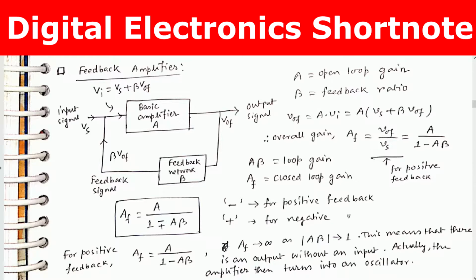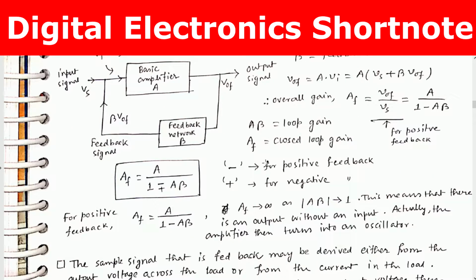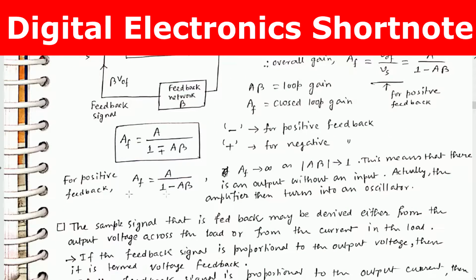Overall gain AF equals V0F by Vs. This is, for positive feedback, A by 1 minus A beta. A beta is called loop gain, and AF is called closed loop gain. A negative sign will appear here for positive feedback, and a positive sign will appear here for negative feedback. For positive feedback, we get AF equals A by 1 minus A beta. AF goes to infinity as A beta goes to 1. This means that there is an output without any input. Actually the amplifier then turns into an oscillator. This is the Barkhausen criterion: A beta equals 1.